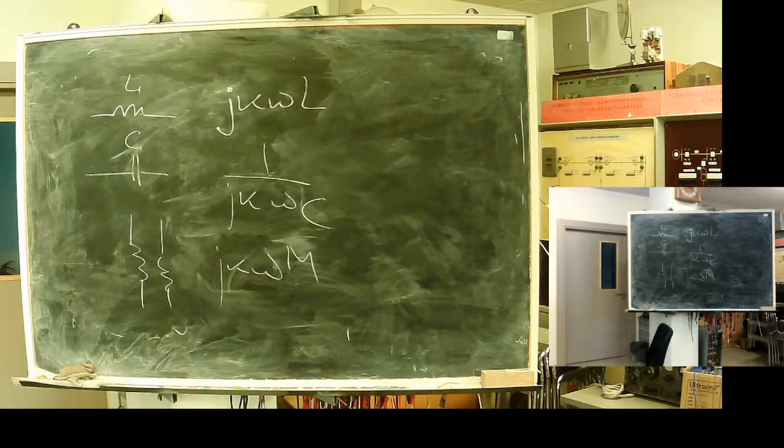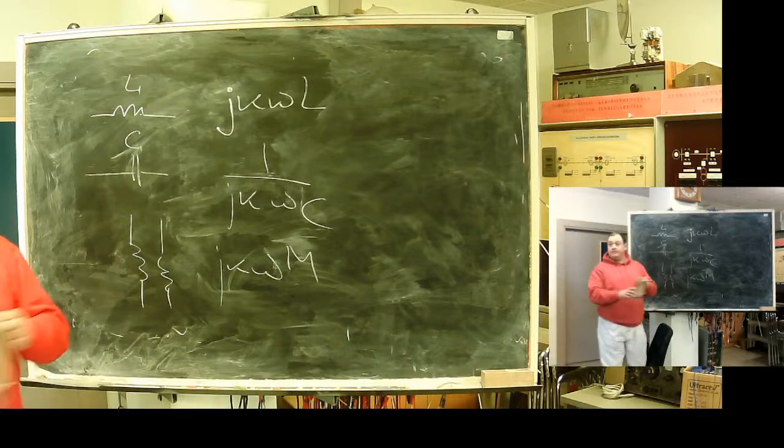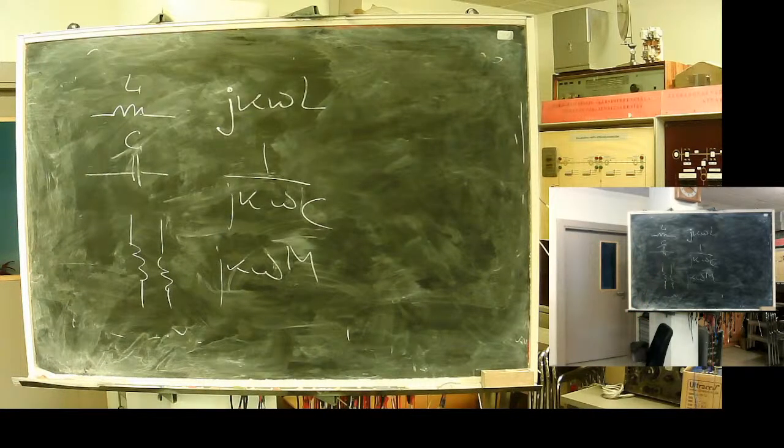Professor, why isn't there a K inside the equation? Because it's 1, 2, 3, right? Yes, because the first harmonic is 50 hertz, second 100, third 150. That's why the frequency changes. This one counts the number of the harmonic, and for each harmonic, the frequency changes and the resistance matrix is recalculated.